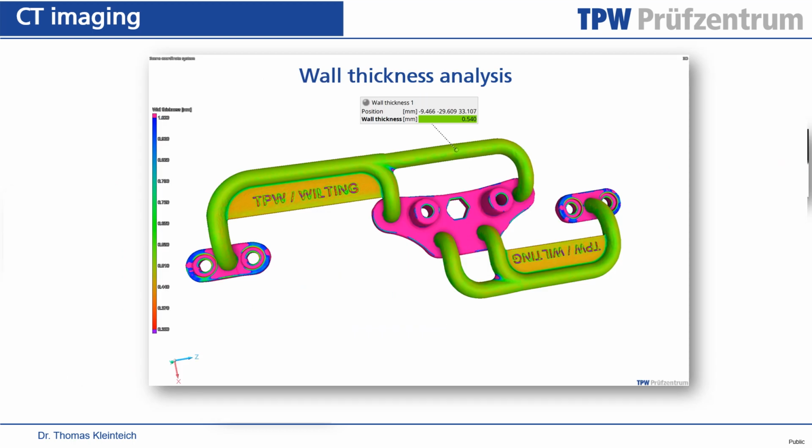And finally, wall thickness, and you might have already guessed it, there's also possibilities to automatically measure the wall thickness throughout the entire part geometry and to return it, and also to have some false color coded representation that in this case does not show shape deviations but shows a false color coding of different wall thicknesses, and you will immediately see if there's critical regions where this wall thickness drops, and you can have measurements all over the part to study wall thickness.